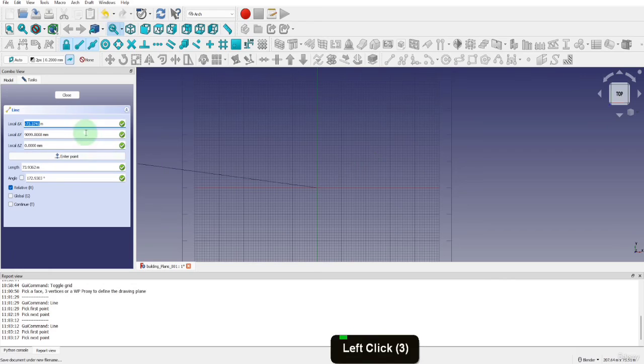Hover back over the properties. In the X, let's input 3200 and make sure there is an mm to specify millimeters and not meters. Then press return. Then we can input 0 in the Y and Z. At this stage, we could press return and complete the operation. Alternatively, in this scene, we can press X and that will specify the other two axes will be 0.